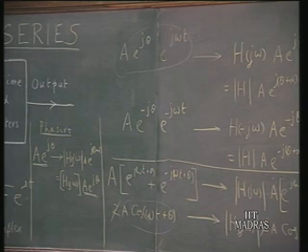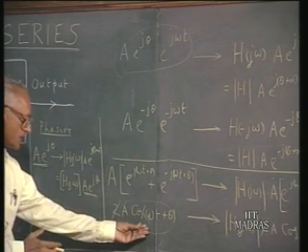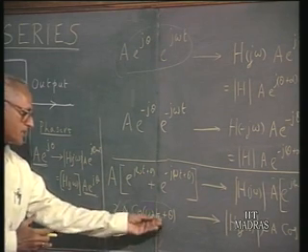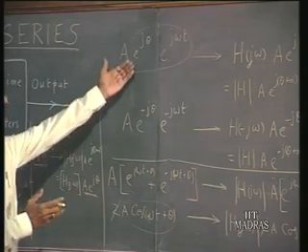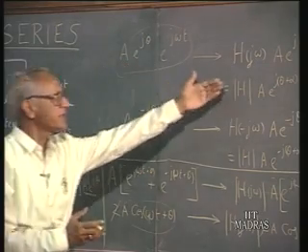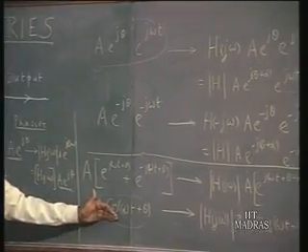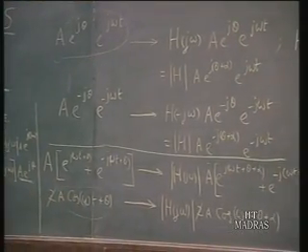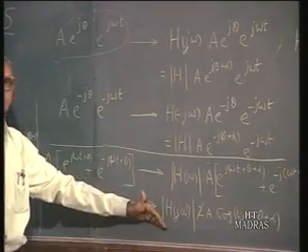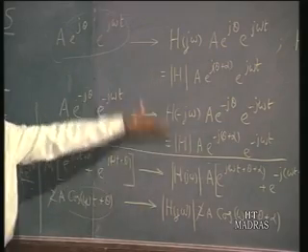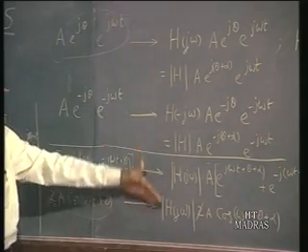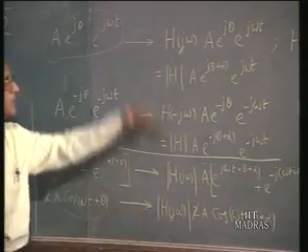So this is the characteristic signal whose real part is the signal which we are using. Now, instead of using this actual signal A cos(ωt plus θ), suppose we assume the characteristic signal was present, this would have been the response. But since the real part of this signal is what we are actually using, the output will be the real part of that, and that is what is happening here. Even though I have put these 2 steps here, actually what you can see is this is the real part of this.